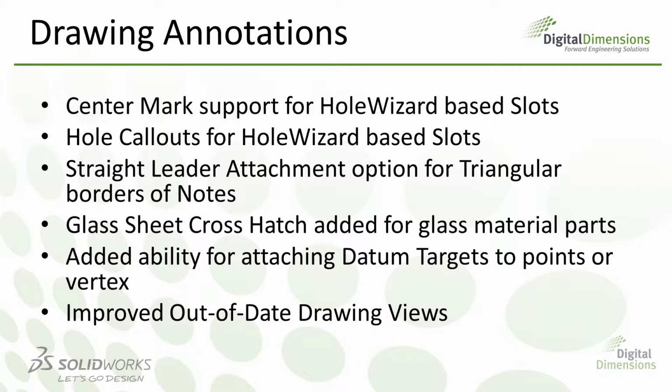And finally, they've added some further capabilities for out-of-date drawing views. Specifically that when you make a change in your model such that the drawing needs to be rebuilt, but you don't want to pay that rebuild penalty, SolidWorks is now not going to obscure the drawing view from your ability to edit the drawing view, so you'll be able to add notes or whatever else needs to happen, and then when you're ready you can pay that rebuild price.